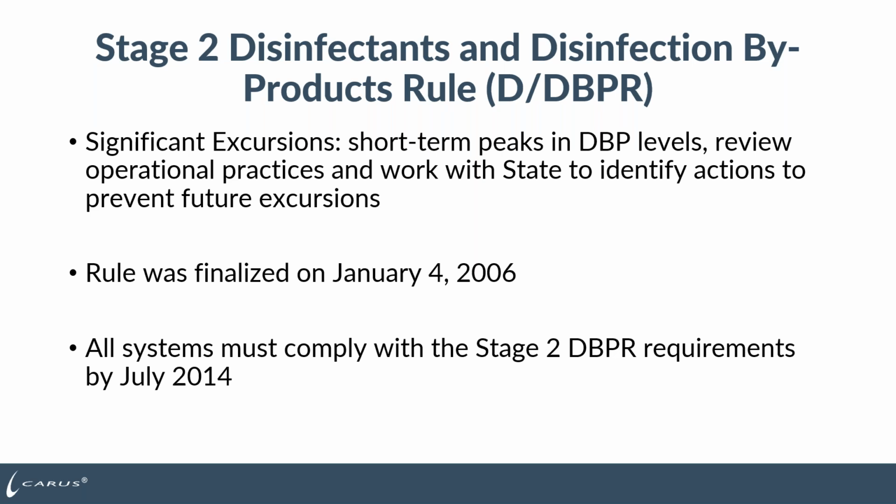So this could be, we don't feed year round, and now we're going to feed year round to make sure the numbers are always low. Was it a coagulation issue, and we need to do something to help with organics removal? Basically, look at your water quality treatment process and determine the best way to get consistent results so you don't have spikes that throw you out of compliance.